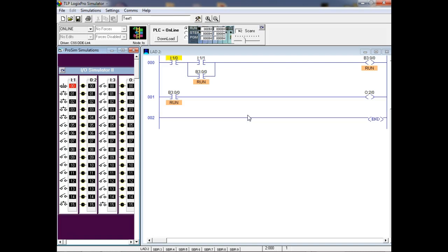So anytime it says a master start-stop switch, let's see how this says it. This says a master switch is the main start-stop switch. And that's still true. Well, that's not true. We're using how many switches? Two. But understand B3. What's B3? Does this guy generate an output?